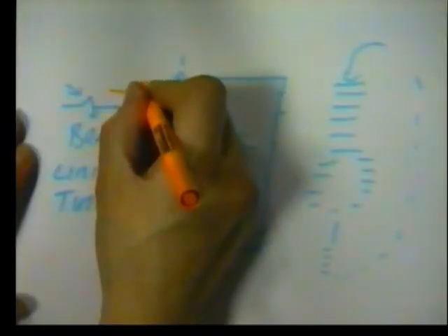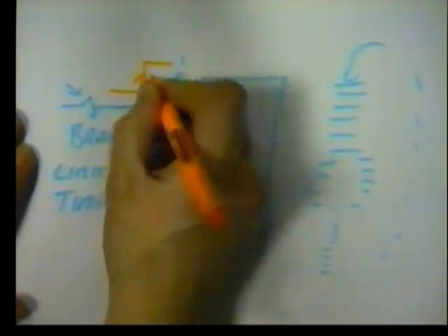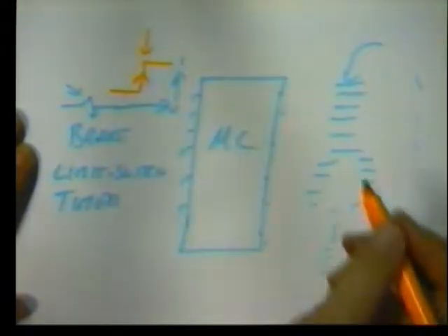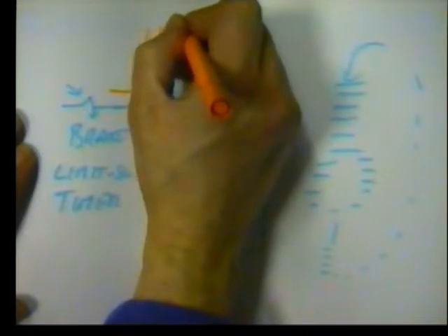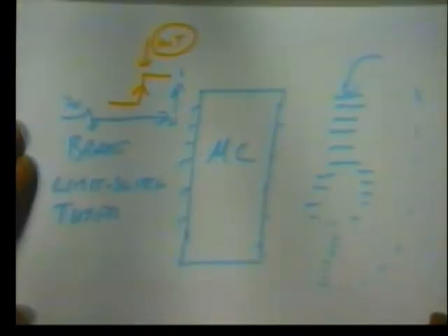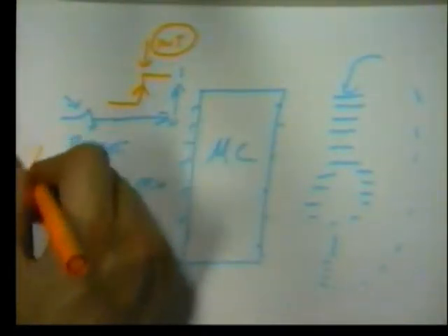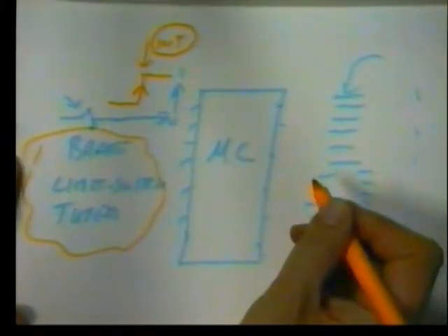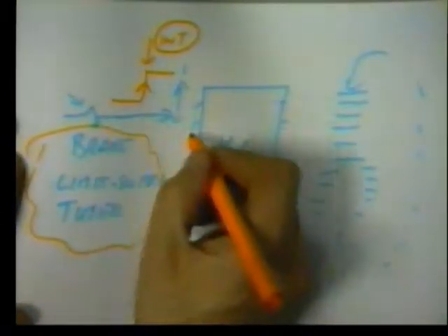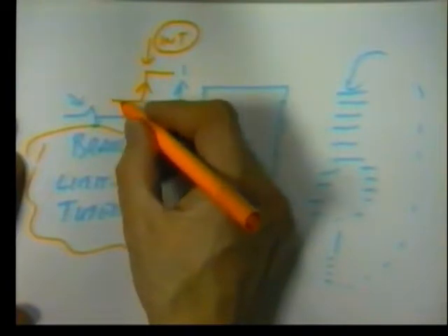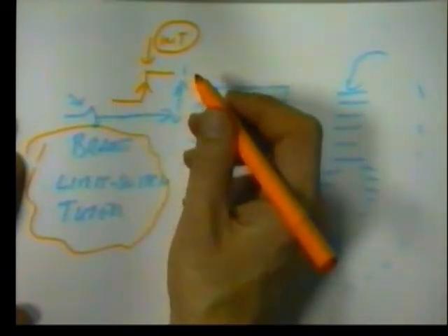What happens in binary terms is that the signal went from a low to a high with a rising edge. That instance is the instance of the actual interrupt. Whatever the source was, there are many different sources of different types of interrupt. It will be signaled to the computer by a rising edge signal.